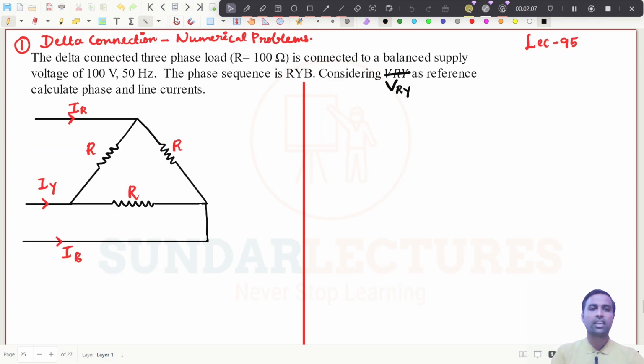So now this is the given question. You see the delta connected 3-phase load, where R is 100 ohms, that is the given data, is connected to a balanced supply voltage of 100 volts. The voltage between these two points is 100 volts. Whatever voltage they have given you, you have to take it as the line voltage, the base case we have seen also in the star connected load system. Then the phase sequence is RYB, and considering VRY as reference, calculate the phase and the line currents.